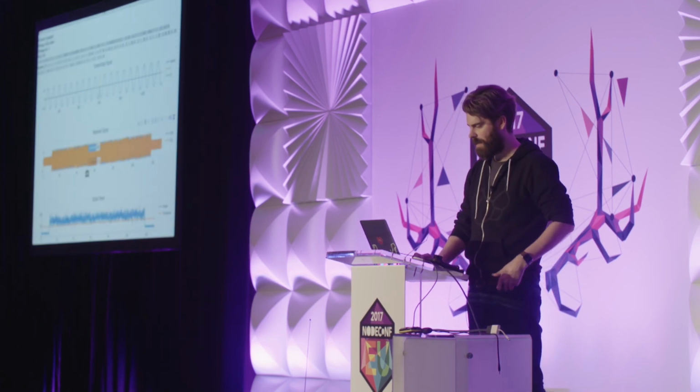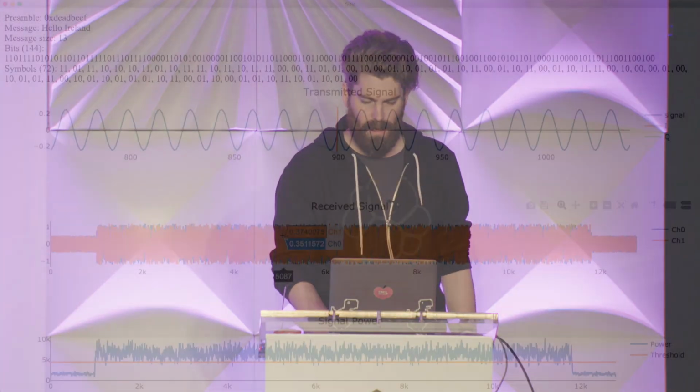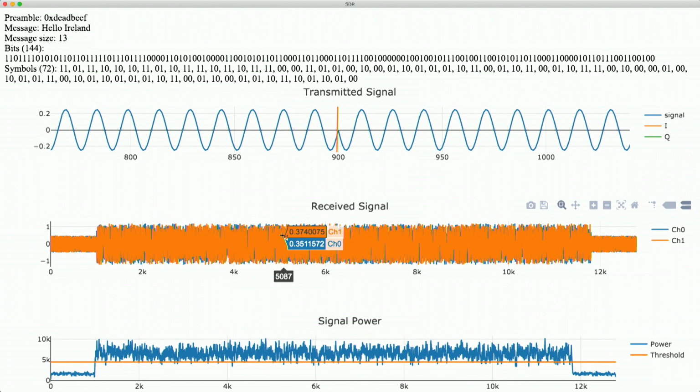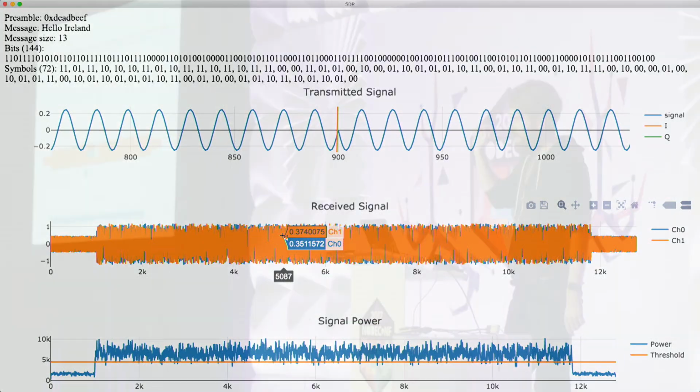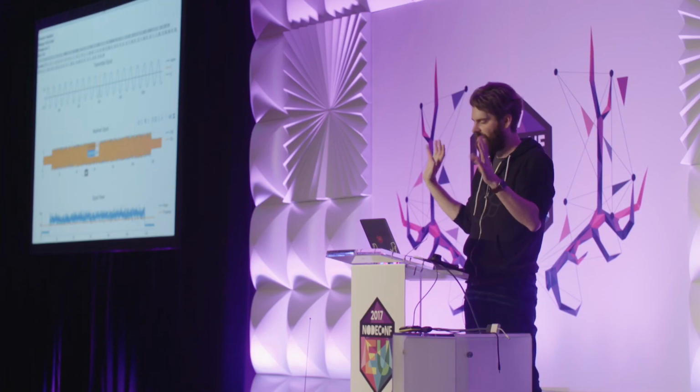And then I have the receive signal. In this case, I've cheated a little bit. I've hard-coded the amplitude where I consider that a signal is coming in, so I have a minimum threshold. Normally, you would have to do what's called auto gain control, where the further away the sender is from the receiver, the fainter the signal is. So you have to artificially compensate for that to get a uniform gain across the entire radio spectrum. But I've cheated a little bit here.